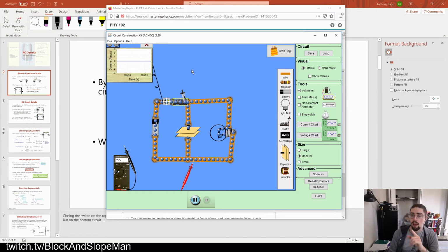And the entire point of the capacitor is to rapidly ramp down that potential so that it's not just a sudden cutoff of the power. It's got a little bit of time and, it's a rapid decrease, but rather than being a cliff, it's a very, very steep hill. And that's oftentimes enough to just help save electronics from getting damaged.